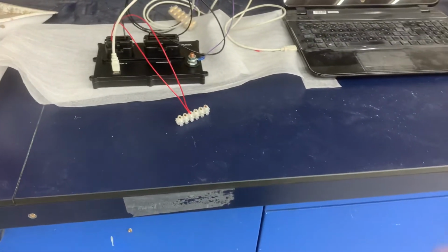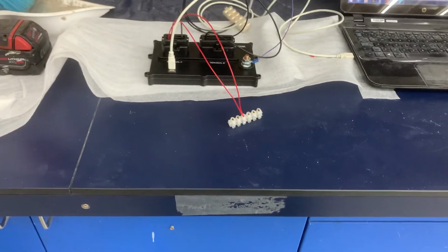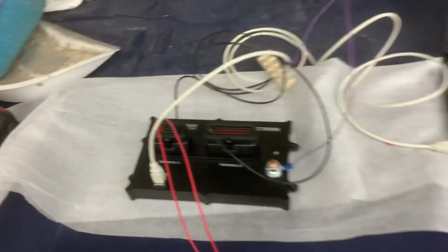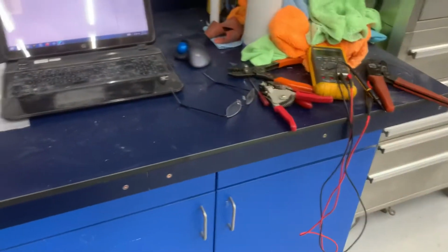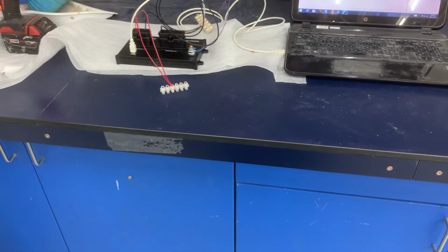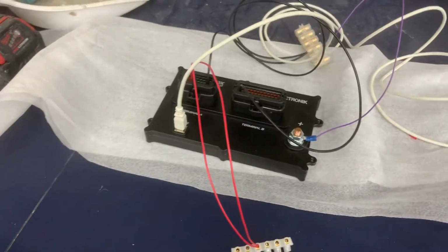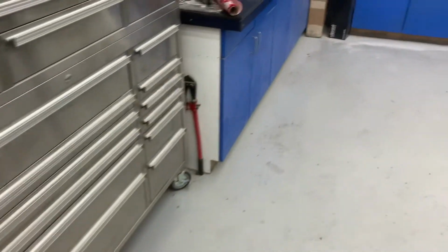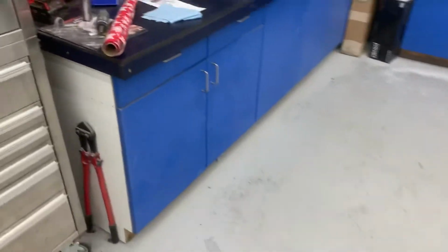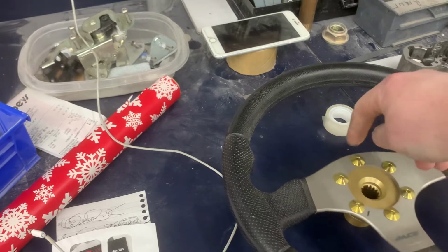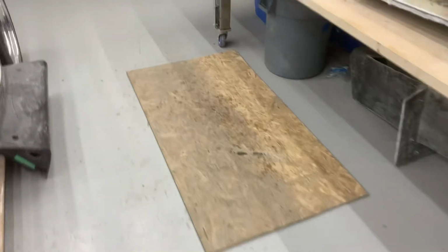So we'll have to have a sort of curly cable wrap around the column, just to make sure, as this won't be wireless. I have confirmed that you can disconnect and reconnect a CAN device off the network without causing any harm, as long as it's not the end of the CAN line with the terminating resistor, which is perfectly fine. Because obviously the steering wheel will be disconnected or not, as well as having the removable part of the steering wheel there, we'll have to have an electrical connection as well. So that's on that side.